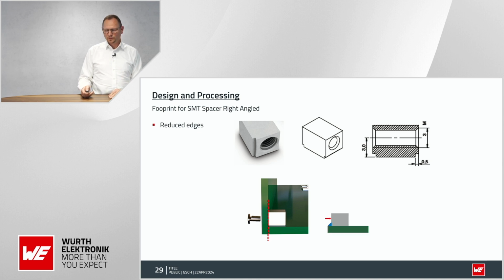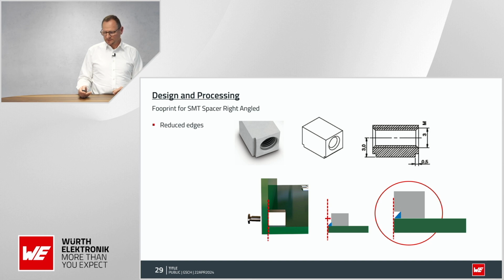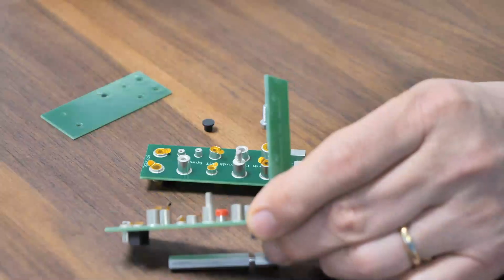therefore if we have this traditionally without this gap, this would lead to misalignment, of course, that the meniscus would appear here, and of course on that side as well, but this would draw the component away from the edge. So at the end, the solution looks more like this. So we still have the meniscus, we still have the strength that the meniscus gives us, but we can achieve a clear 90 degree angle.